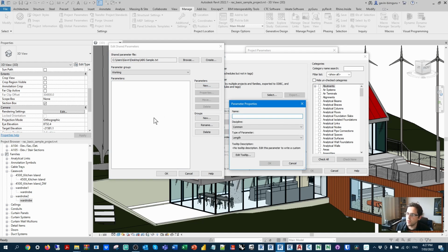The first parameter we want to add in this case is going to be the cost rate. So how are we actually measuring the object, or the takeoff rate, I should say. So I'm just going to give this a prefix, APG underscore takeoff rate. And I'm going to make this a text-based parameter. Notice I usually use, in this case, I believe this is called Pascal case, where you capitalize where you wish to break your data, and I usually use an underscore for a big data break.